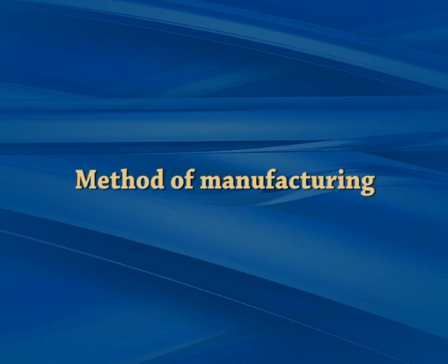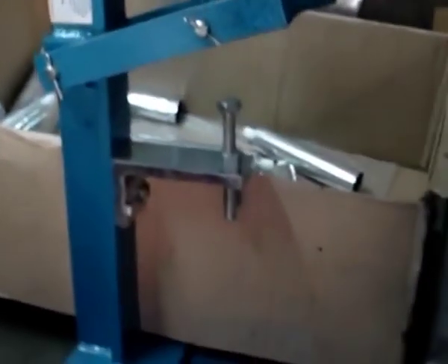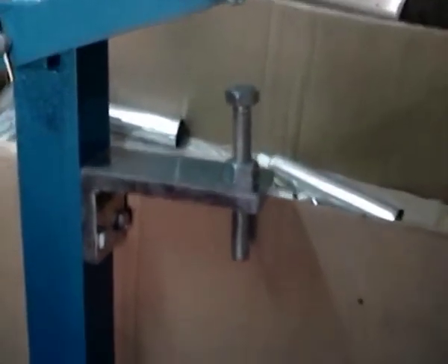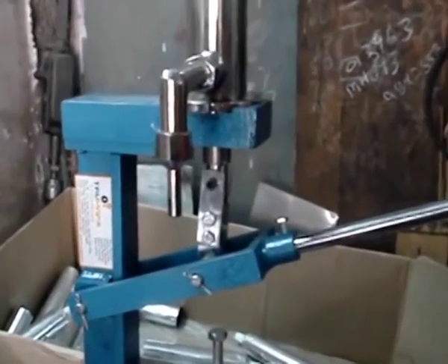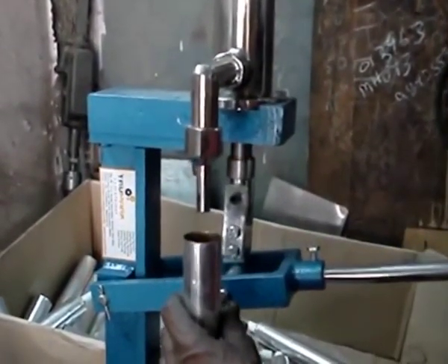Methods of manufacturing: A. The basic extrusion process is used for metal collapsible tubes, except that the slugs used are rings rather than discs, and the female die which holds the slug is shaped so that the metal is forced downwards into the die to form the shoulder and nozzle as well as upward around the plunger.